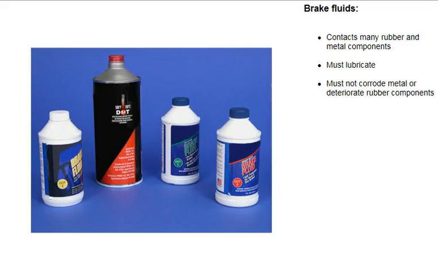Brake fluids come into contact with a number of parts. They must not corrode metal or deteriorate rubber brake components such as the cylinder pistons and seals. In fact, the fluid should be able to lubricate those components.